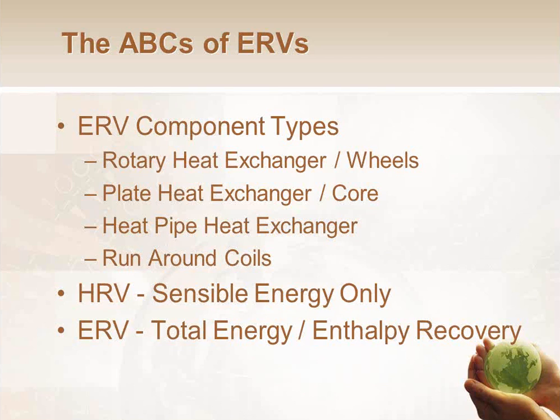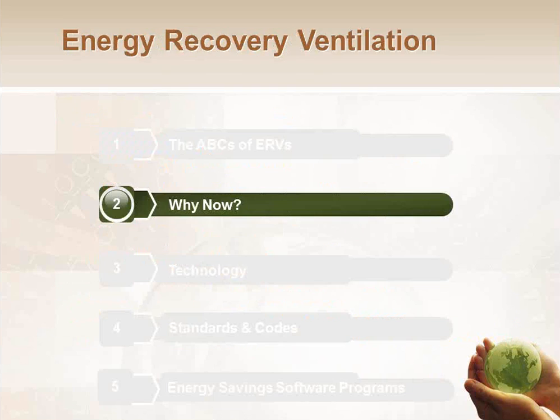And I already mentioned ERV versus HRV. HRV is heat recovery ventilator. It only does sensible energy recovery, no latent, so it does no humidification, no dehumidification, just heat and cool. ERV does all 4: heat, cool, dehumidification, and humidification.